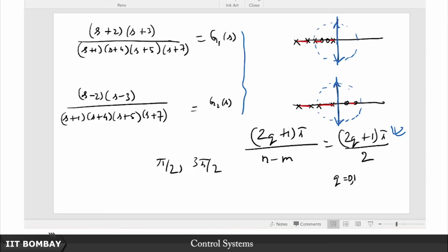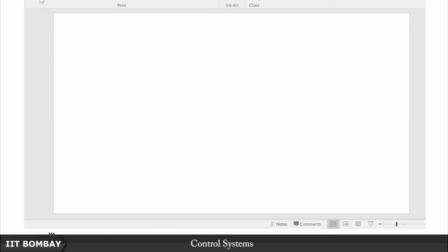Of course, you might still argue, well, the idea of an asymptote is to eventually figure out where the closed loop poles migrate when k is large enough. So why are you bothered with figuring out how these asymptotes behave for smaller values of k? And there is some logic in that. But we would say that we still want to have a better idea of where to start this asymptote from. And it is this motivation that leads us to figuring out that these two systems should have their asymptotes originating or intersecting with the real axis at different points, not both be at the origin.